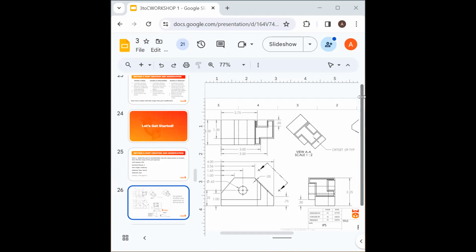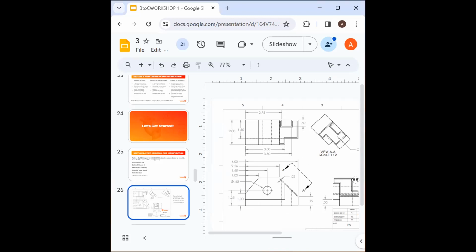Okay, sorry. The reason why I added the circle to this sketch is because when I extrude it, I can select which shaded region I want specifically, and then I don't have to go back and do a cut extrude, right? So I'll just skip over that step. To get the depth, so to speak, of what I want, I'm going to look at the dimensions from here, and notice that it says 2 inches, so I'm going to click on 2 inches here.